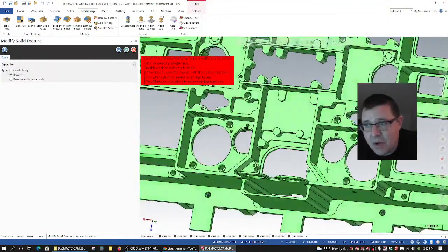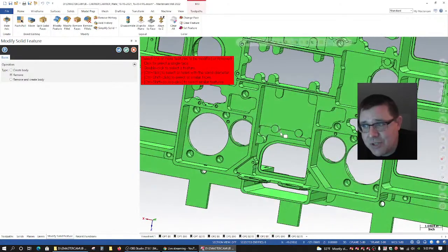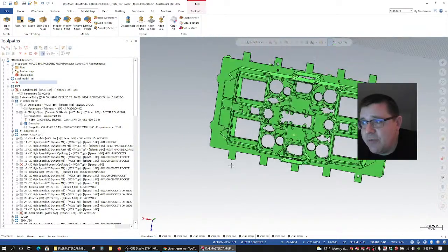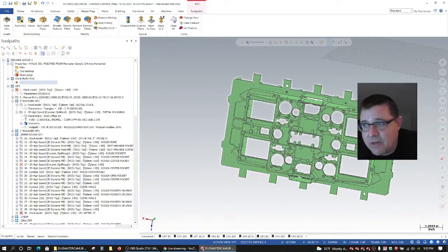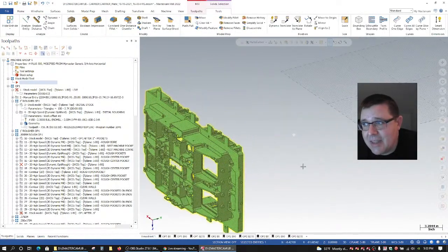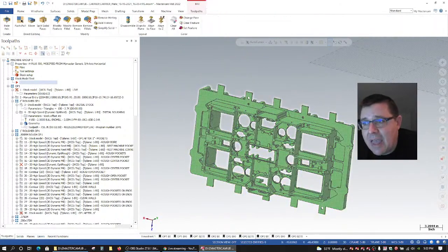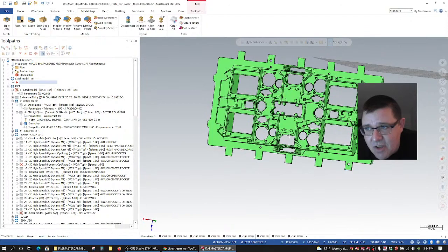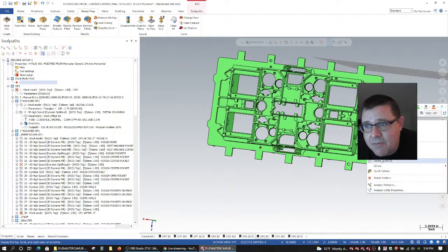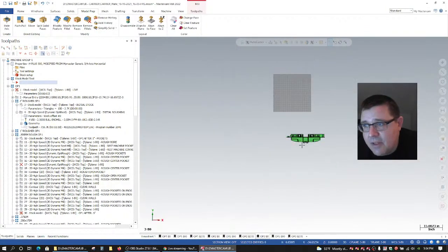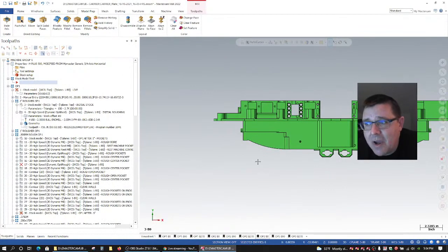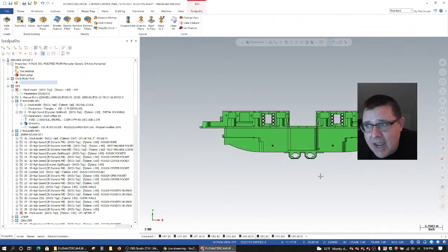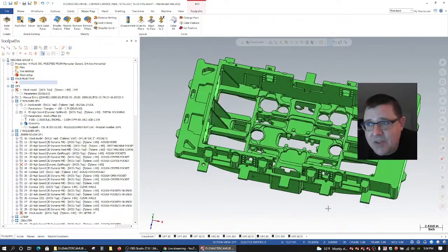And the other thing is when you go to actually toolpath this, there's a huge difference, or can be a huge difference, between selecting the entire model and simply selecting the faces of the model that are visible in the view you're cutting in. So if this is the view I'm cutting in, I don't necessarily want to select every single face on the solid.